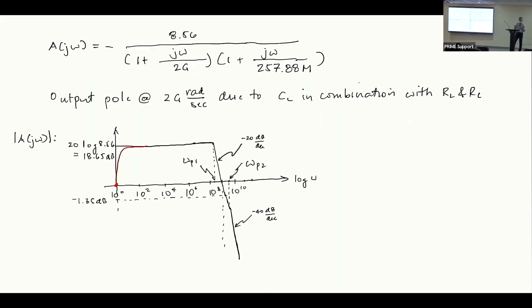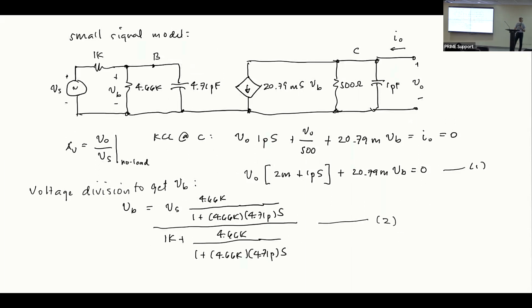If I already know the gain of this amplifier, then when I add C sub mu, I will just put the 1 plus A C sub mu in parallel with the input, and the 1 plus 1 over A C sub mu in parallel with the output. And my process now becomes simpler. So you can do that.